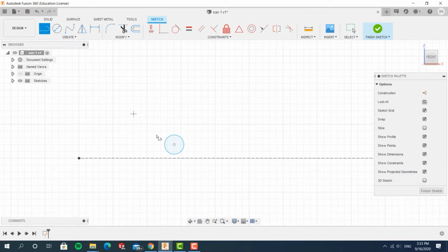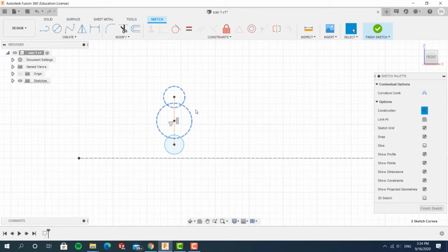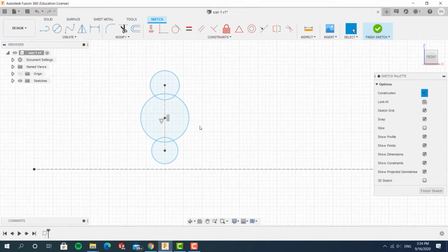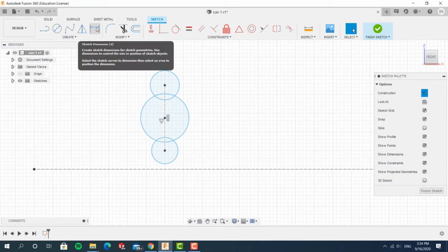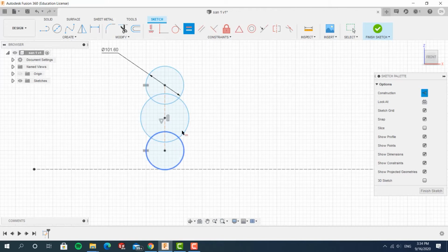The rule of thumb that I was taught is basically to get the distance between the wheels to be about 3/4 of the diameter of the ball. But because for the FRC 2020 game, the actual ball is pretty soft, you can deform it a whole lot. So I actually went with a bit less than 3/4. The ball is 7 inches in diameter. The distance between the wheels is going to be 5 inches.